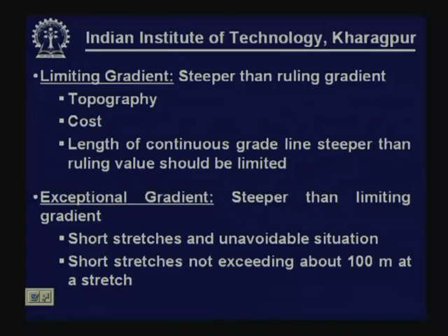But since exceptional gradients are much steeper, we should not use exceptional gradient for a continuous length of the stretch. It can be used only for a short stretch, normally not exceeding 100 meter at a stretch. So, only for short length it is permissible.